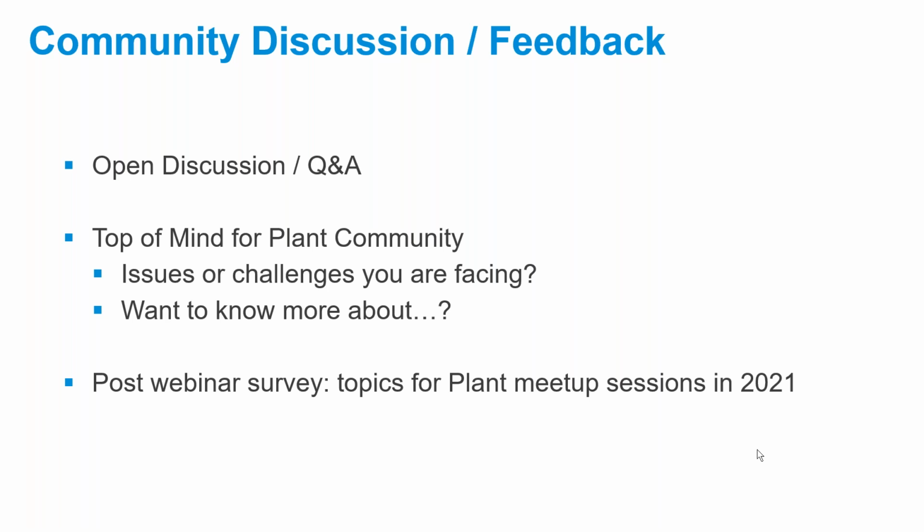So I'll address that first: if you have a SQLite project and you're sharing it with multiple users, that's not a good workflow. It's actually strongly recommended against because it's a file-based database, and so you're going to get disconnects and lost information quite a bit if you have multiple users working in the same SQLite project database.